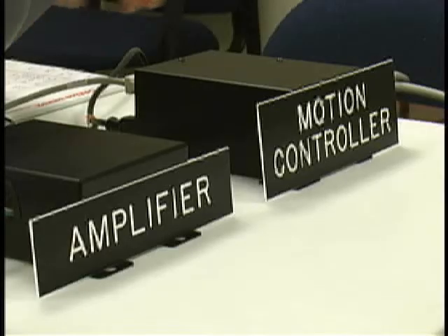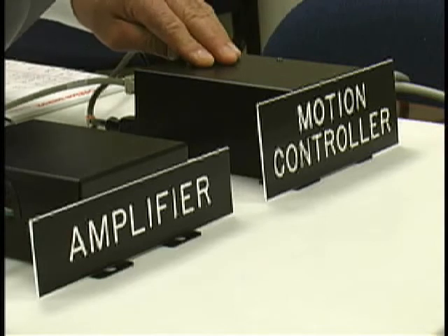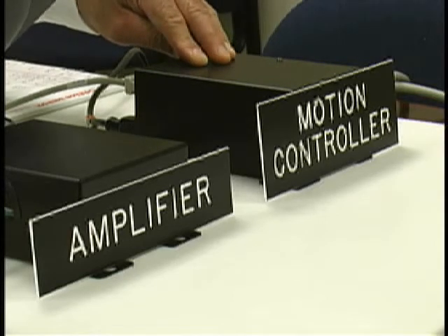So there are quite a few modes of motion that the Galil controller could supply, addressing the needs of the users. The next function I would like to describe is the stored program in the controller. The controller has a memory allocated for application programs. So I could start with an application program, download it to the controller, and execute it from the controller. This way the host would not be involved in the details of the motion. The host would be free to perform other functions.